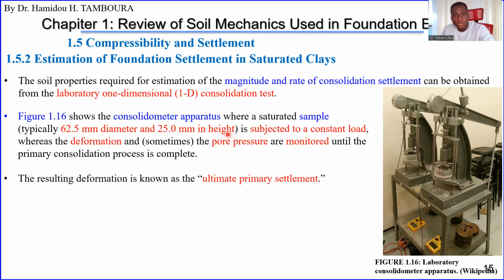And during this, we record the deformation and also sometimes pore pressure. The deformation that results from the test is called the ultimate primary settlement. And during this, we will drain water from everywhere, from all directions.